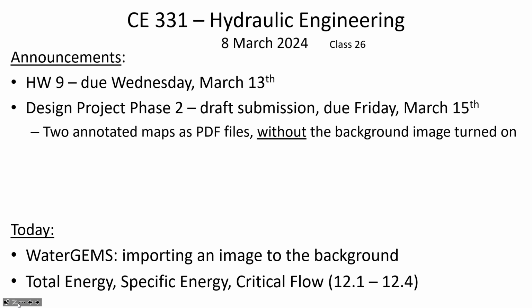The other thing that's on your plate right now is phase 2 of the design project, which is using WaterGEMS in order to size the pipe network. So we've done a couple of in-class demos to familiarize you with that software. I'm going to show you how to bring up a map in the background today so that you can draw your pipe network on top of a map that's scaled, and then the lengths are accurate and you don't have to do any user-defined lengths.